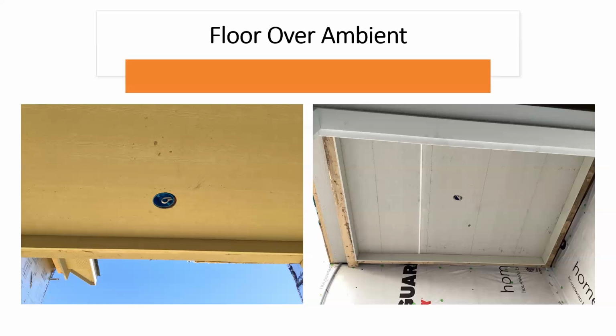The biggest problem with floors over anything, even if they're insulated, is whether the insulation is in proper and permanent contact with the correct surface. Is it permanently held in place? These cornice boards should actually be removed. Insulation must be verified to be touching the right surface, as well as being held permanently in place, not just friction fitted. So most builders, the cornice guys get ahead.